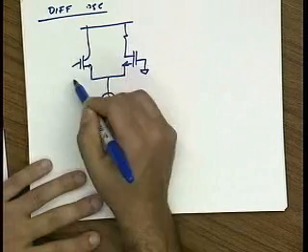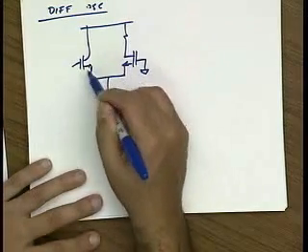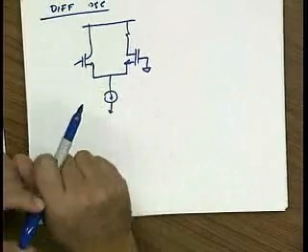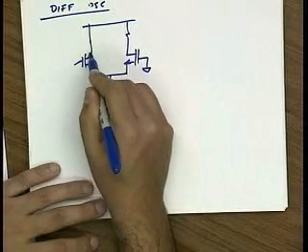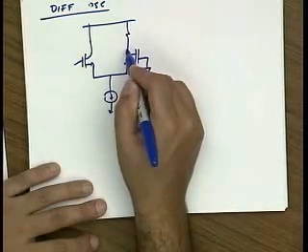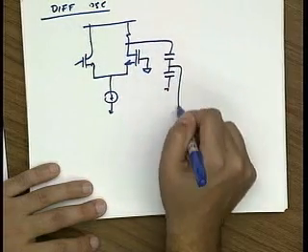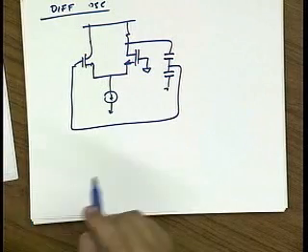It's broadband because the follower stage is very broadband, and this stage is driven by low source impedance because of the 1/gm impedance seen looking back. So this is a two-stage amplifier, and in fact the gain from here to here is positive. So I can just take this point, feed it back, and hook it up back into the input. And I have positive feedback.